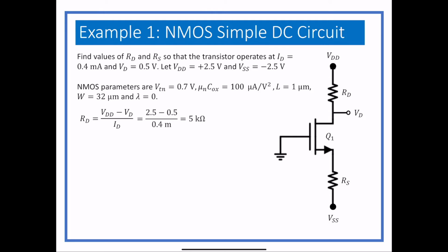So that's what makes MOSFETs a little more tricky than some other types of circuits. So the overdrive voltage, we've done this before, is the square root of ID times 2L over Kn prime W, and that's just taking the ID equation and flipping it around. And we know all of those values already. They've all been given to us, so we just plug them in, and we get half a volt for the overdrive voltage.